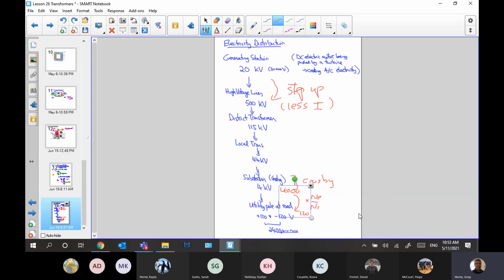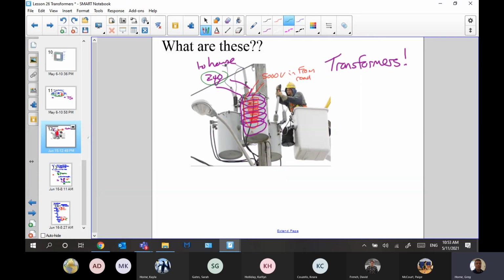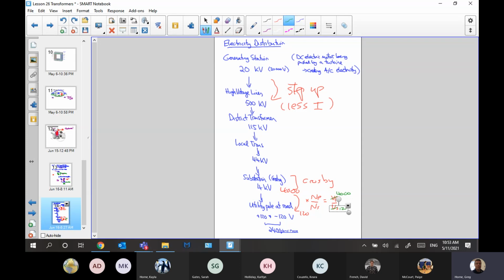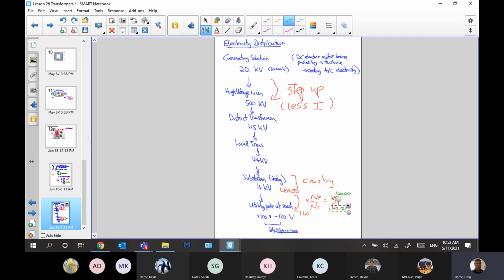And you can obviously tell that would be equal to the primary voltage over the secondary voltage, right? So you can tell what the numbers would be. That would be 4,000 over 120. I'm interchanging between saying 120 and 240. I apologize for that, but houses have 240 and 120 available. In this case, I was more honest about how it's actually 240. When you use only half of it, like houses are wired, you're looking at 120. Don't let that confuse you, though.